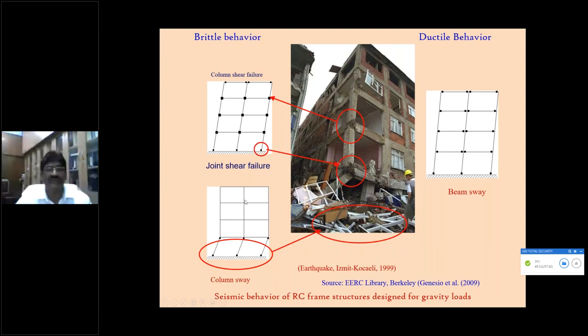So therefore, you have to analyze the building, assess the capacity, compare with the forces acting, and then think about what needs to be done. Something like retrofitting, globally or locally. Locally, maybe not possible because it is already existing and inbuilt, but maybe globally you can think about it. In the global way, either you can provide a parallel bracing system using steel, or add shear walls externally